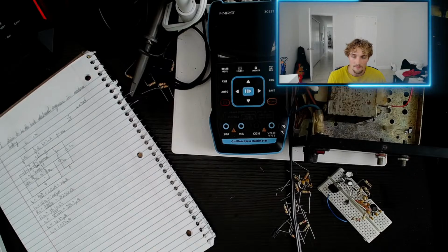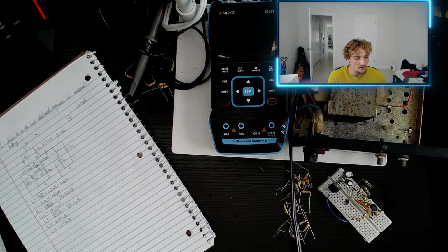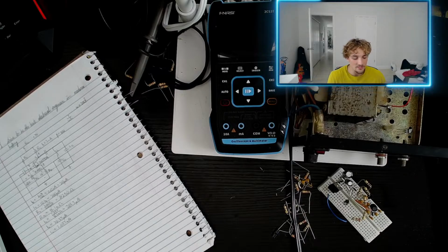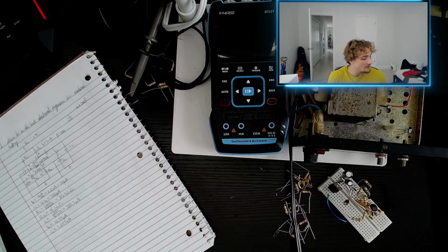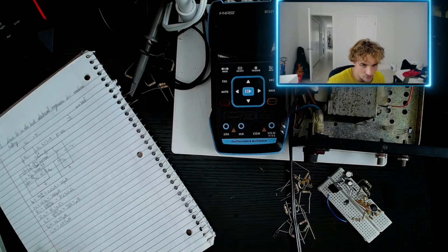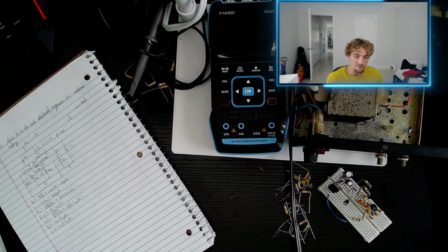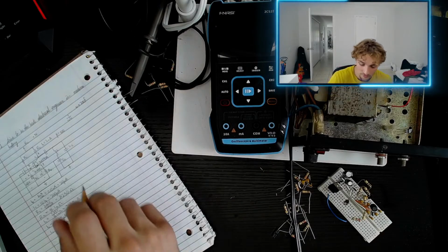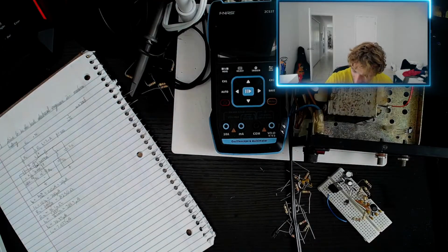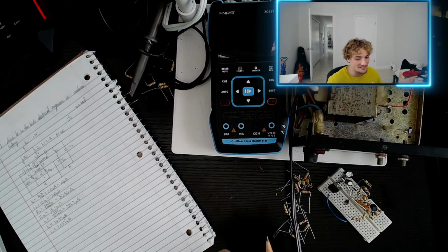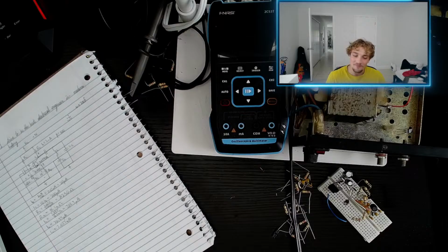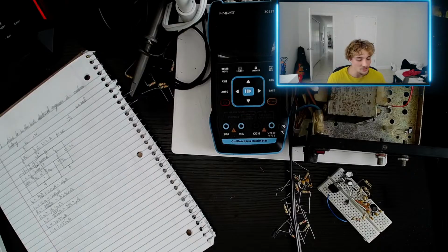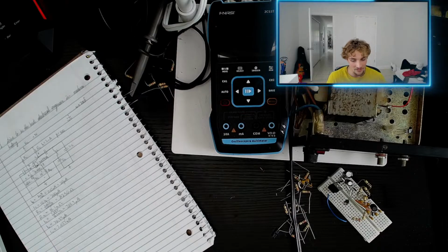2.25 volts. That maybe could be our maximum swing, maximum output before we perceive any distortion. That might be true, but that's pretty much what we're shooting for: we want to allow maximum swing so that we don't clip any of our sine wave, because our sine wave is going to be the output for this oscillator. And then in the future, I want to run it through a buffer and then to a Schmitt trigger in order to convert it into a square wave.